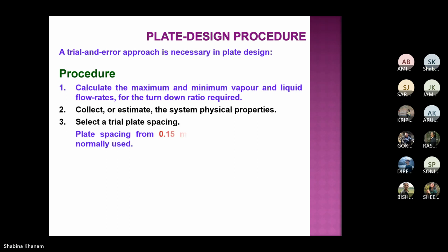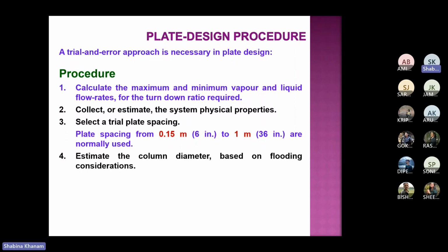So that would be trial, because you need to assume any value. Okay, so plate spacing moves from 0.15 to 1 meter, which are normally used. You can choose the plate spacing between this range, but for a better start, we have like 0.5 meter or so plate spacing. 0.45, 0.5, like this you can consider. Okay, next is